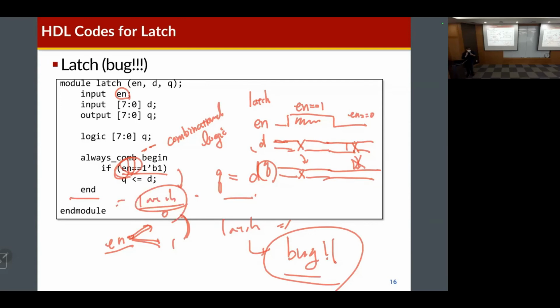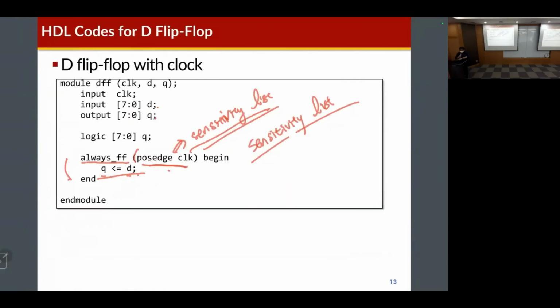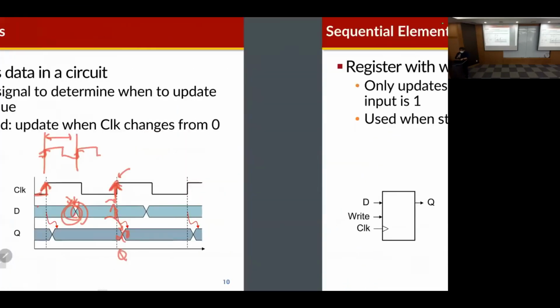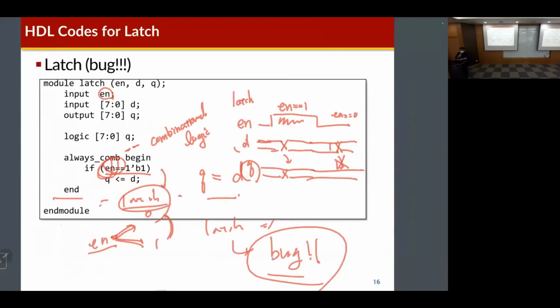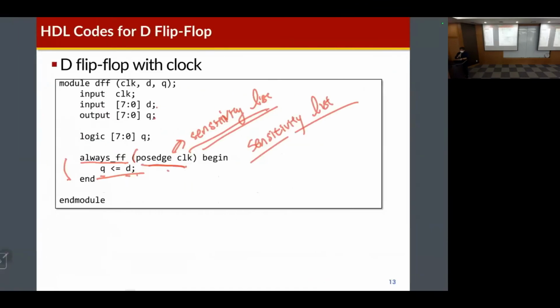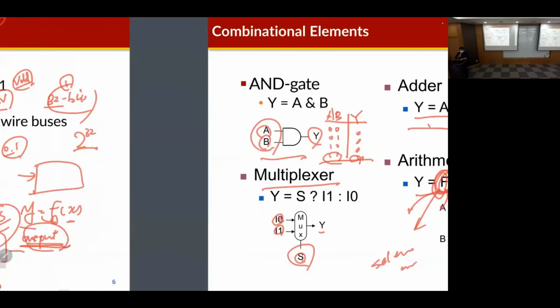You must avoid generating latch in your design. This is a must, okay? Because the latch is only used for special cases. This is the very basic fundamental of system design, and I hope this is helpful for doing your lab assignment.